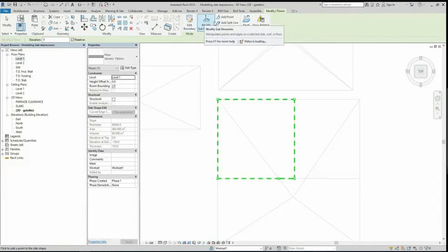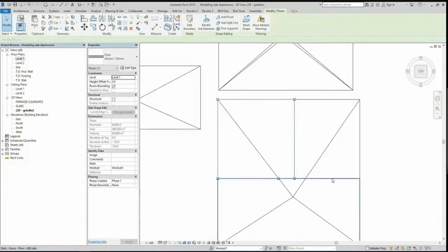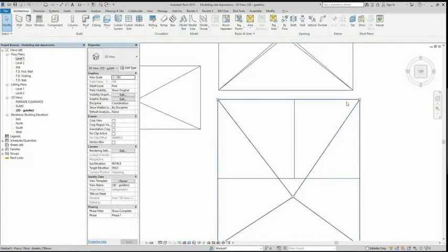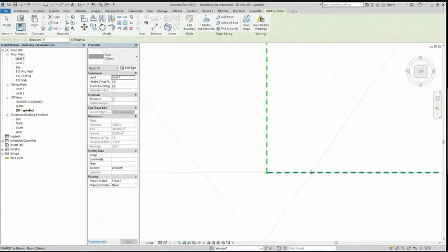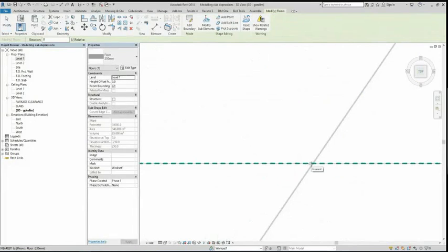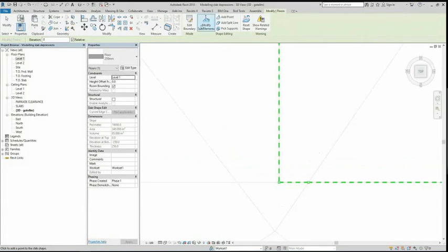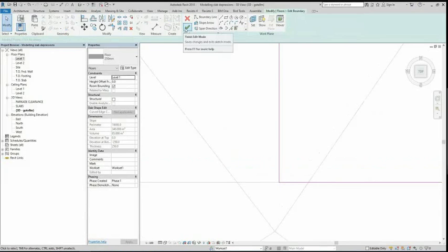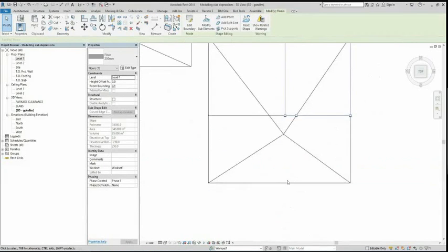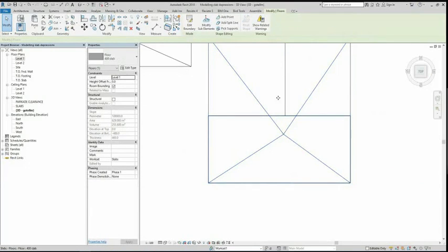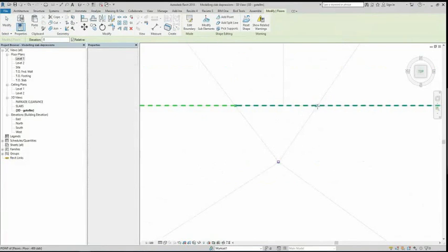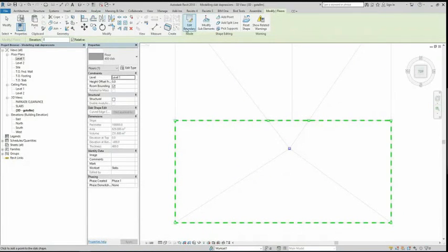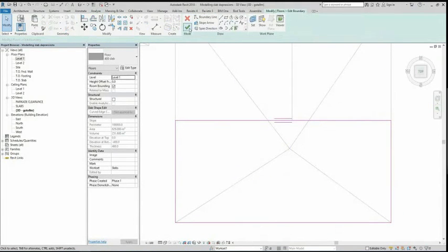So now that I've done that, I'm going to click Edit Boundary, done, and then I'm going to repeat that same step for the other 2 slabs. So add a point. Finish, and then lastly, the thickest slab. So I want to add one obviously where the floor drain is, and then one for the other 2 contour lines.